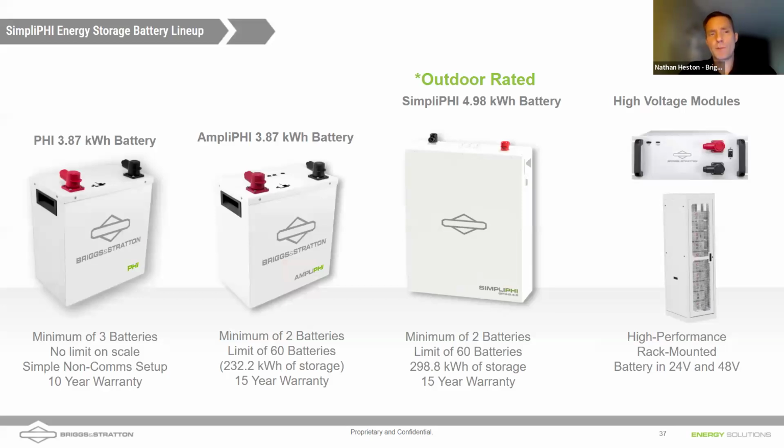I do want to point out we only have about 5 minutes left, so I want to save time for questions. We've spoken a lot about our newer battery, but there are a lot of customers that are still doing lead acid replacements. If you look at levelized cost of energy, with a lithium battery you get a lot more usable flow of power and energy through an LFP battery than you would through lead acids.